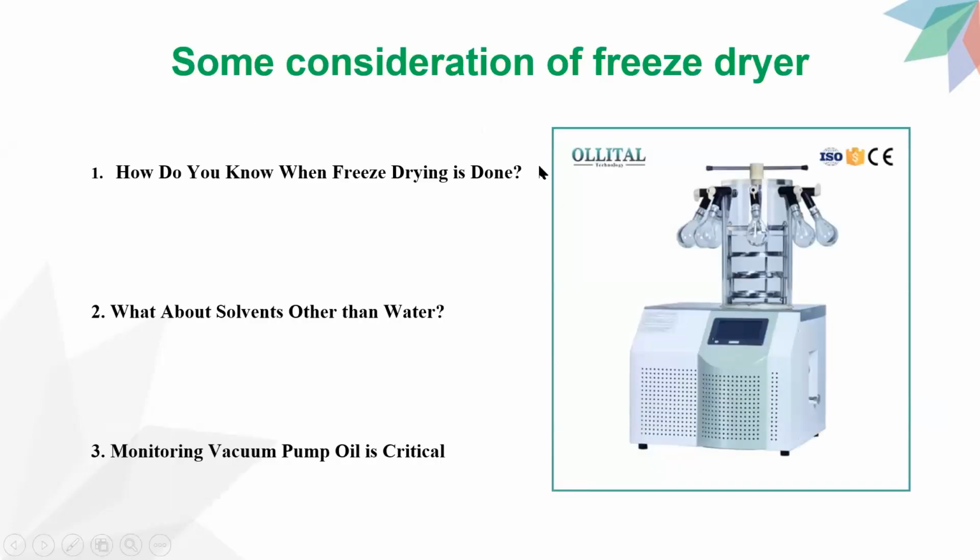When you deal with a freeze dryer, especially the manifold freeze dryer, there are some considerations you should keep in mind. Number one, how do you know when freeze drying is done? Number two, what about solvents other than water? Number three, monitoring vacuum pump oil is critical.